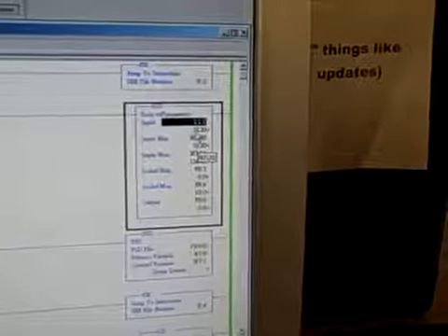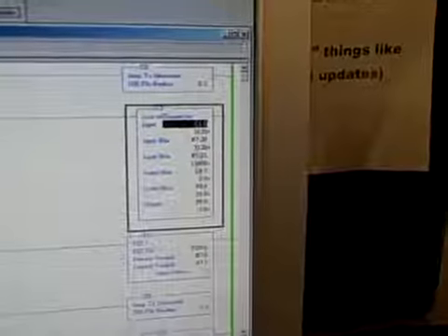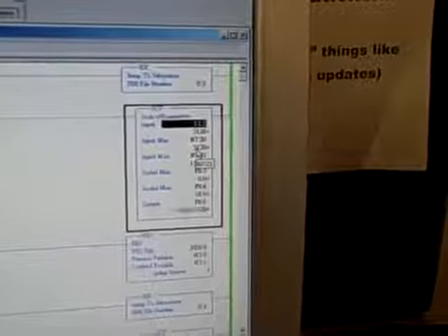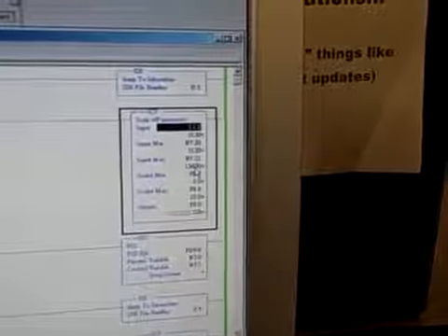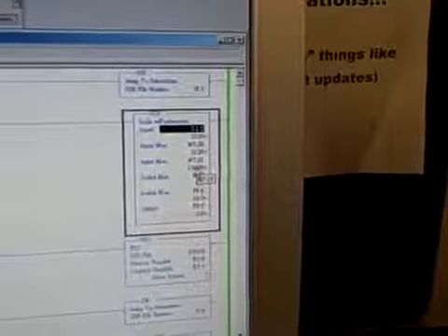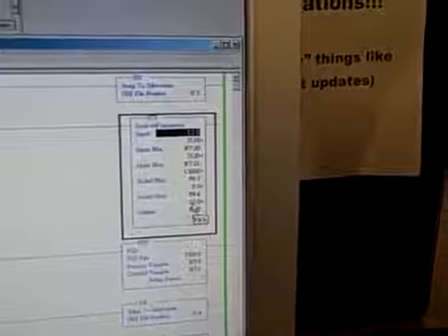The raw count values here, the 3120 or the 15600, come from the A to D card. 3120 is nominally what you should get with 4 milliamps of current, and 15,600 is nominally what you get for 20 milliamps of current. We use a scale instruction here to scale those raw count values into some sort of engineering units that will make more sense on an operator's display.